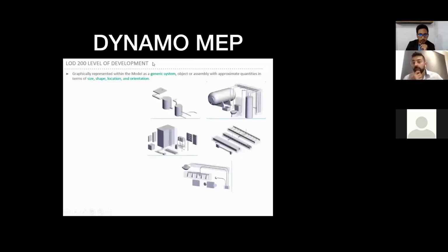Design script will be the coding interface that you will use in Dynamo. If you're writing design script, it will only allow you to shorten up the nodes of Dynamo. You can use it to create variables, but you will be in the same environment of Dynamo, a controlled environment that you can only use for mathematical options. When you go to Python script, you can connect to the Revit API, you can connect to other APIs, and you can create nodes that will mix and match things outside Dynamo and Revit.